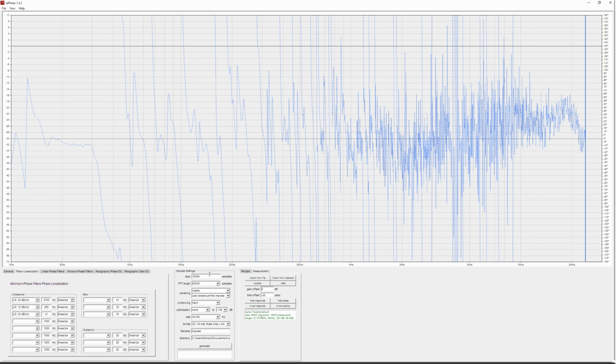At this stage, let's create the FIR filter to correct this speaker's crossovers and box phase shifts. With the unlimited taps of modern convolution engines, you can perfectly replicate the correction. Let's say we have 16,384 taps, 48,000 Hertz sampling rate. Let's keep it at mono, 32 bits IEEE, and call this crossover and box phase correction.